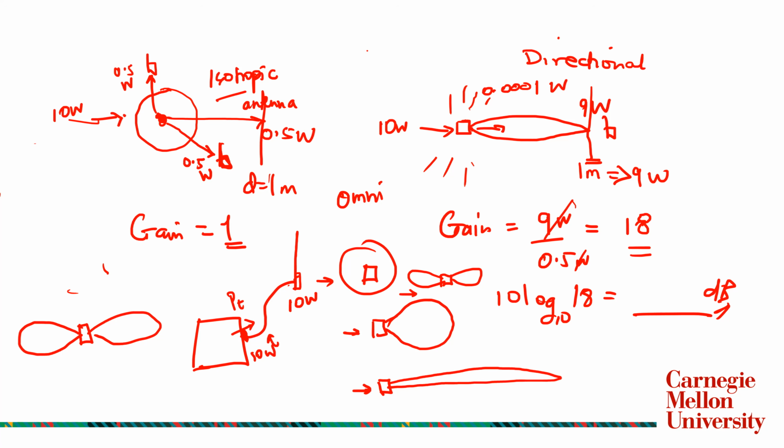And we are going to talk about this again. Felix, why does the negative mean that it receives less power? Not really. The negative is just because it's a loss. So that's why I said at the beginning that my power received is the gains minus the losses. The gains include GT, GR, PT. The losses are what we looked at as the propagation loss.